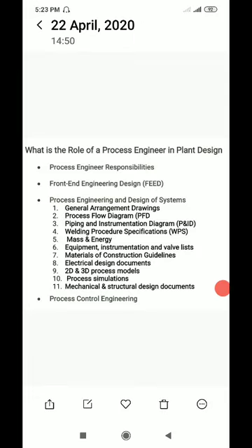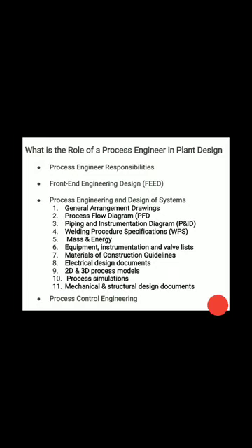Similar to the chemistry of a process, equipment layout and design require a high level of expertise and competence from a process engineer. For example, to maximize accessibility, a process engineer might arrange equipment around the outside edge of the skid to provide both outside access and an inner pathway down the center of the skid. Similarly, logistic factors such as floor space availability in the manufacturing plant must be considered during the process skid design.